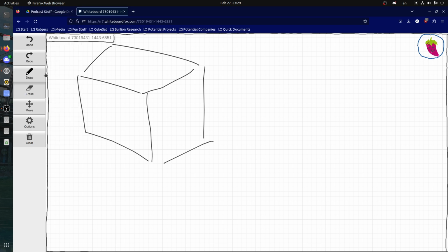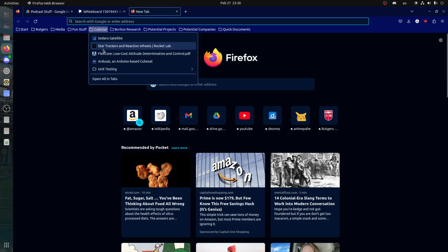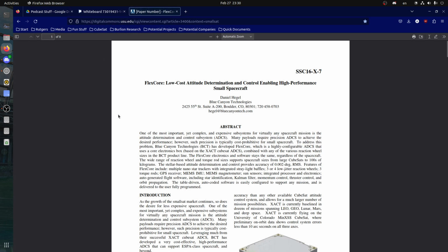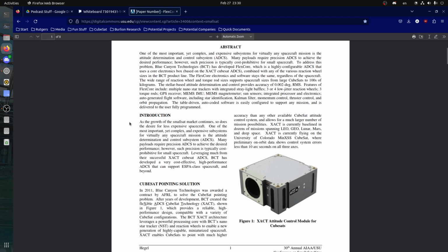Makes sense. Is SPICEsat's ADCS going to have three magnet torquers? Blue Canyon hasn't gotten back to us. Okay, that's fair. So the number of magnet torquers you would like to have, is that according to the pointing budget? The magnet torquers won't have anything to do with the pointing budget. We don't use magnet torquers to do pointing. It's a possibility, but we're not doing it.